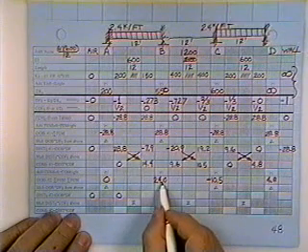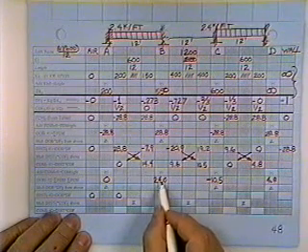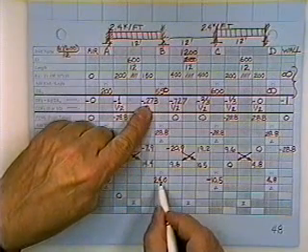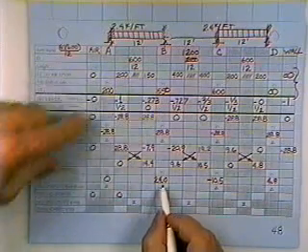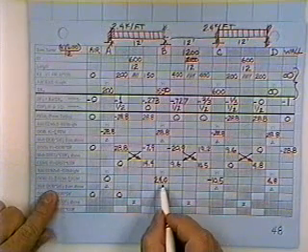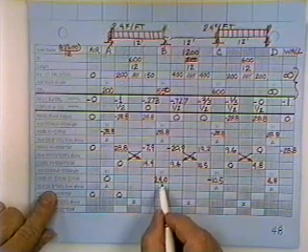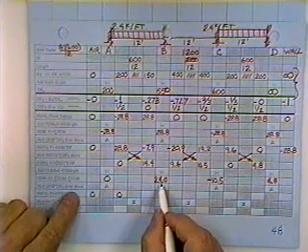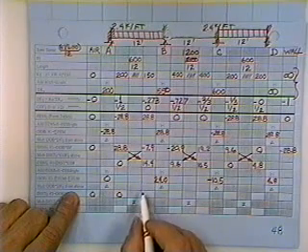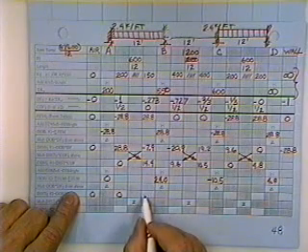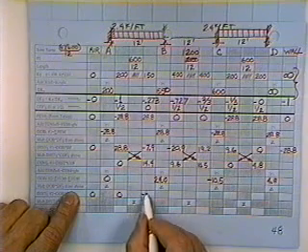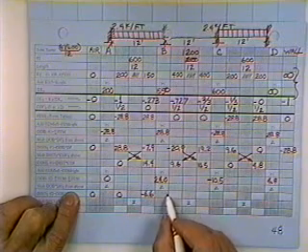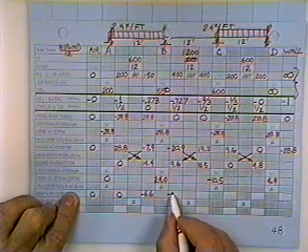All right, now then, the guy at joint B lets go of his wrench, and we let go of the 24. 0.273 of it hooks to the left, and if you'll notice the rule over on the left-hand side, it says, multiply the out of balance, that's the 24, times the distribution factor from above, and that gives us minus 6.6. And sliding to the right of the joint gives us minus 17.5.